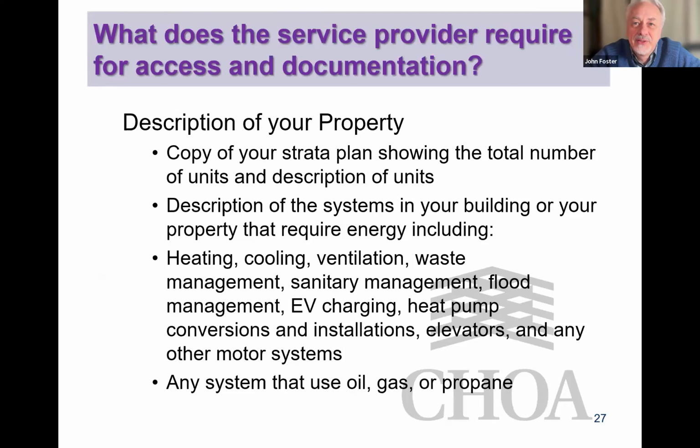And I wanted to also say it's not all doom and gloom and scare. We often get some pleasant surprises that there's a ton of electric capacity unexpectedly. I guess the planners for the building were thinking there'd be a lot more electric heating. In some cases, particularly older apartment buildings, there are things like saunas or pools that were electrically heated and are now just defunct and converted to exercise rooms. So that gives a lot of extra power in your power budget.